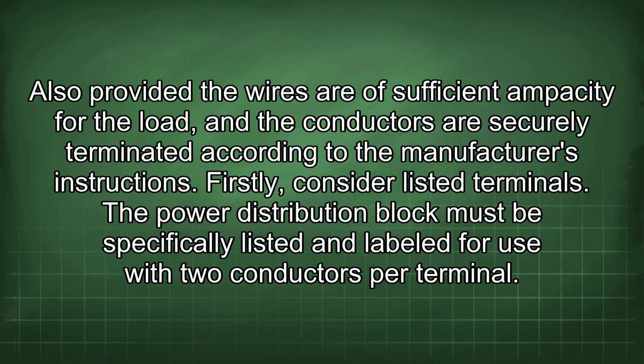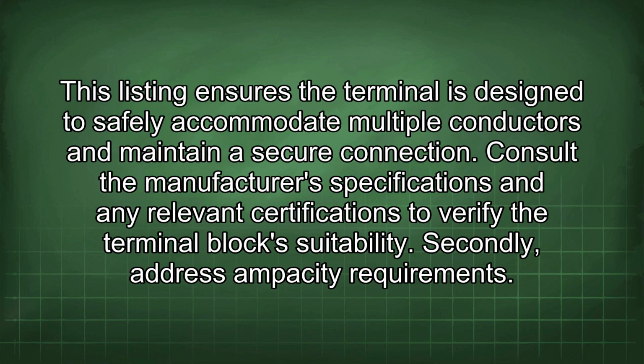The power distribution block must be specifically listed and labeled for use with two conductors per terminal. This listing ensures the terminal is designed to safely accommodate multiple conductors and maintain a secure connection. Consult the manufacturer's specifications and any relevant certifications to verify the terminal block suitability.